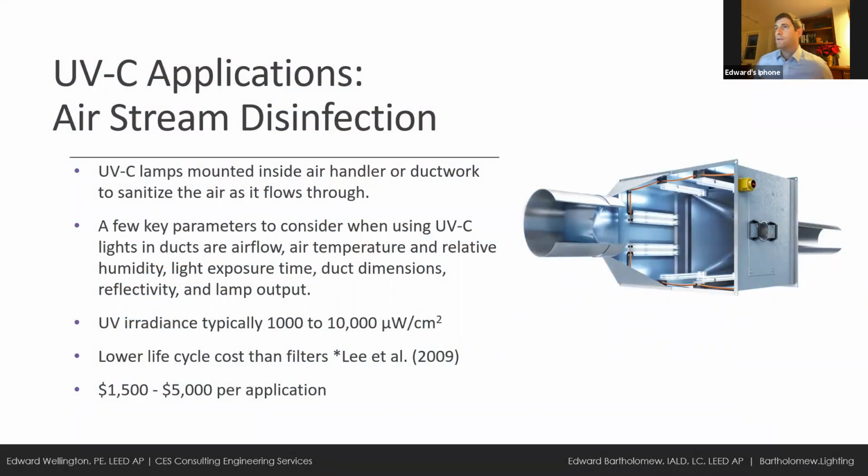The first one is airstream disinfection, which involves mounting UVC lamps inside the ducts or air handlers in your building. This distributes the UVC in all directions, so any air flowing through within line of sight is affected. The key for us when we design these things is considering dose and duration.